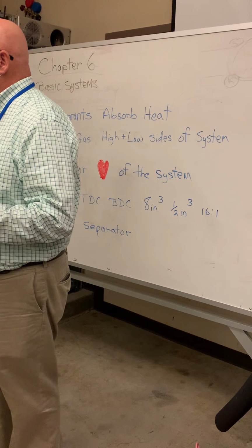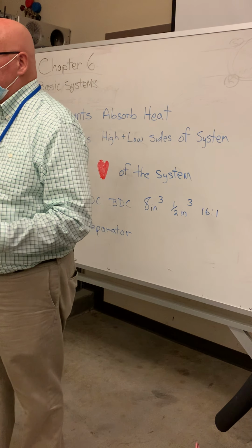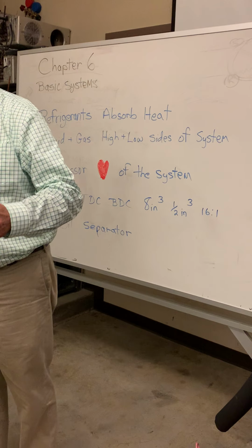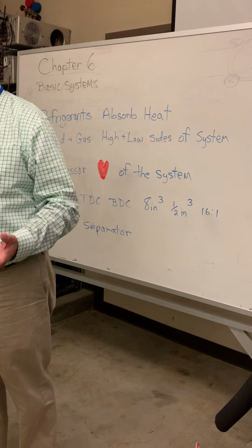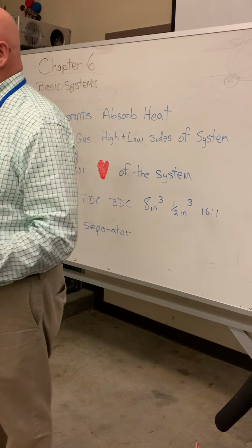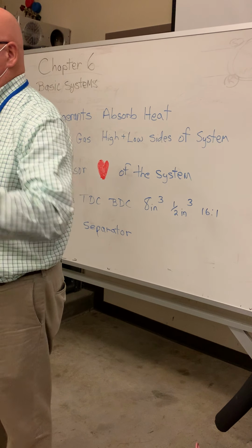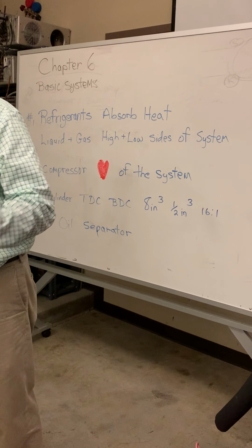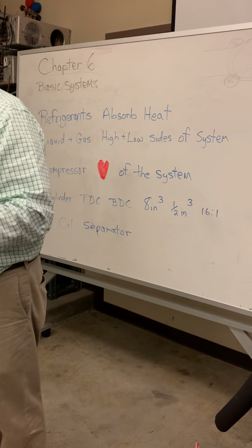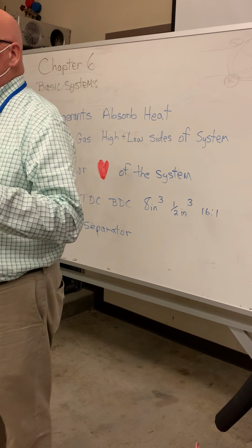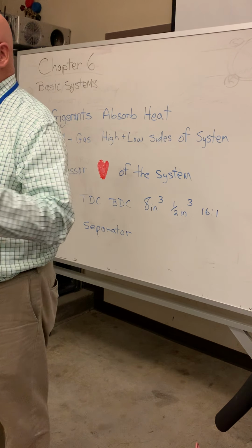If it's one of the old school residential split air conditioning systems like you have at your house, then it's going to move it at a constant flow rate. And if it has a newer system, maybe a ductless system installed in your house, then it's not going to be at a constant rate, it's going to be at a highly variable rate. But whether it's constant or variable, it's still what moves the refrigerant in that system. So a compressor can only handle refrigerant vapor. Or I could say gas in, gas out.